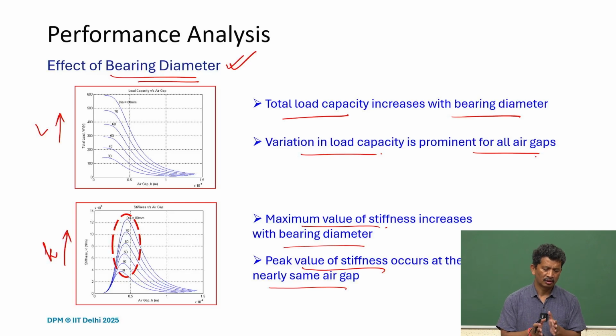So when we are talking about pneumatic hammer or this pneumatic instability, the two things we might be interested in are the supply pressure and the volume of air which is trapped inside. That is the reason we cannot have very big pockets on the bearing surface.